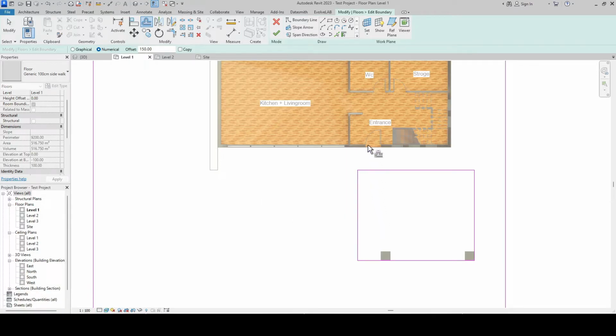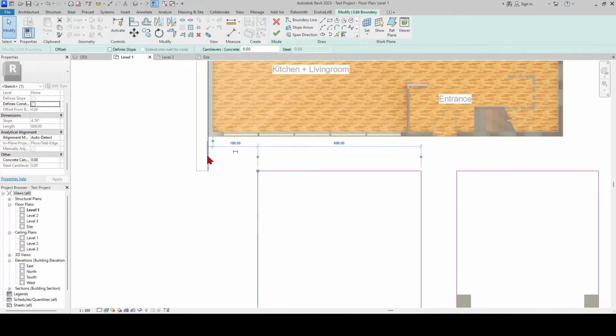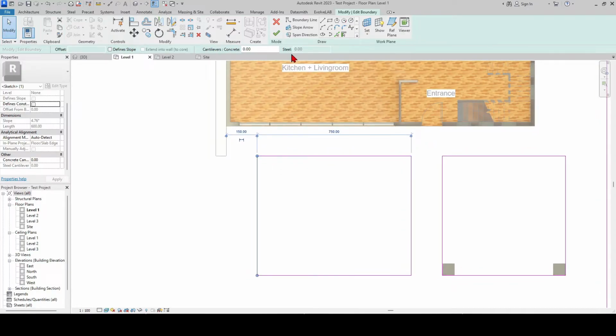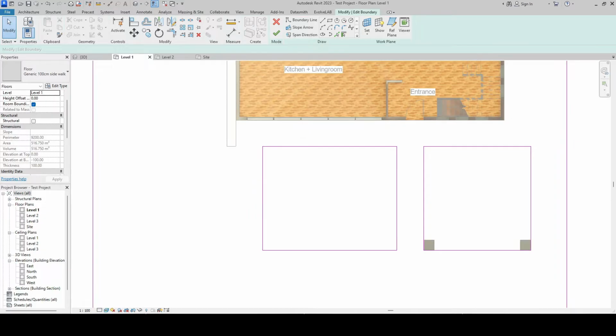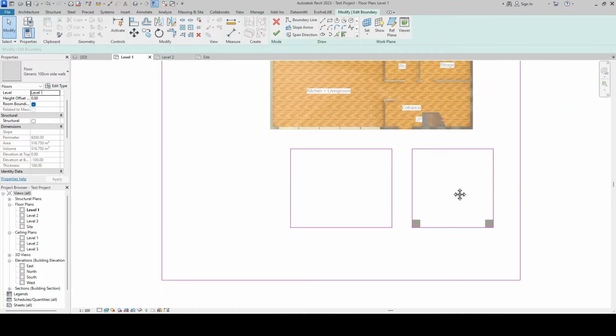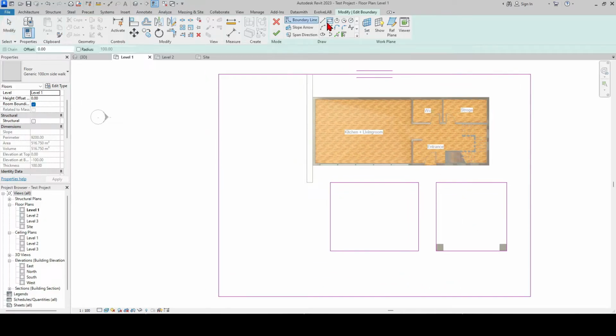Since we don't want the line we are referencing to disappear, we pressed copy after entering the offset command. Let's create some gaps for the green areas as well.